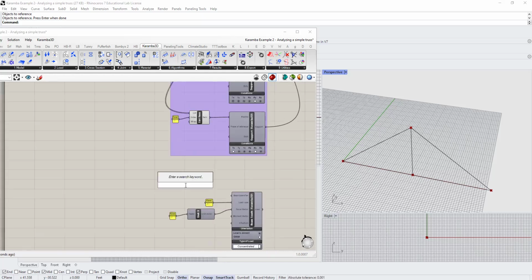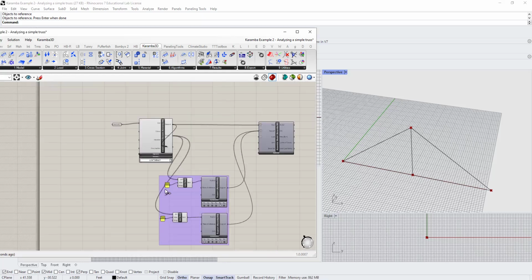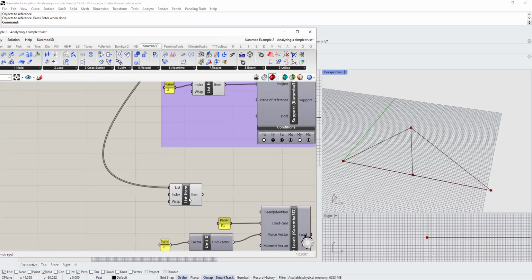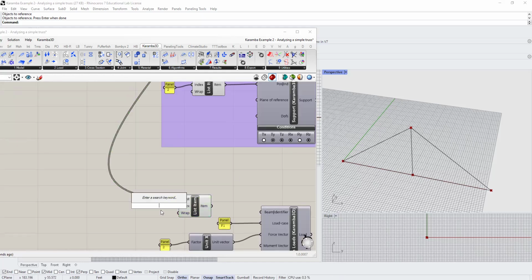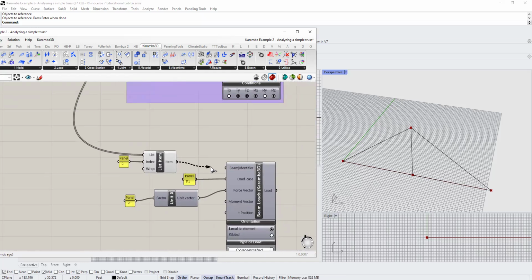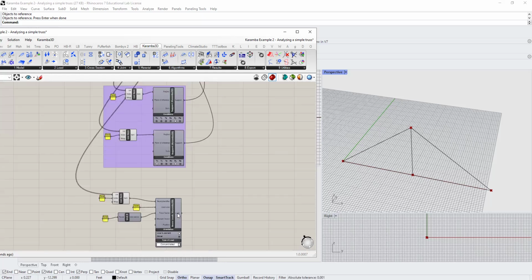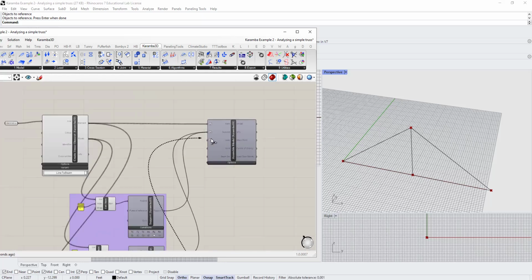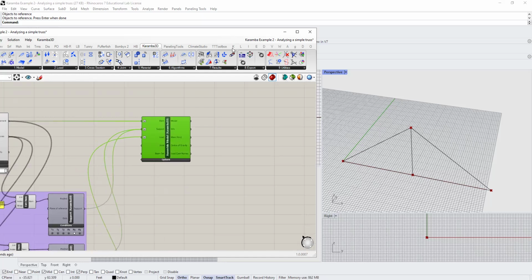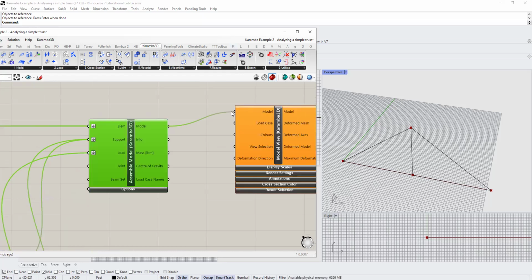First of all, I'm going to drag and drop list item. And I'm going to connect the list of the elements, meaning the list of the beams that I have, the list of the members that I have. And then I will try index 0 to apply the point load to that element. And I'm going to pick the orientation as global so that the X will be along the X axis. And I'm going to connect load to the load input on the assembly model. To view the point load, I'm going to go to the results, model view, and connect model to model.